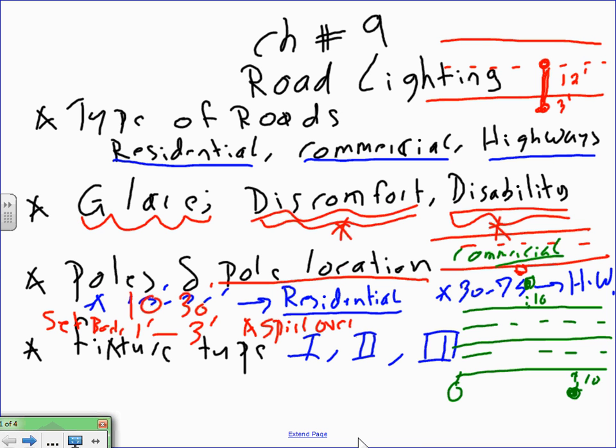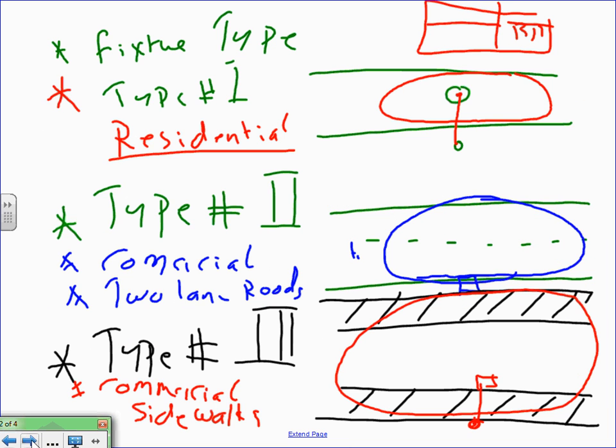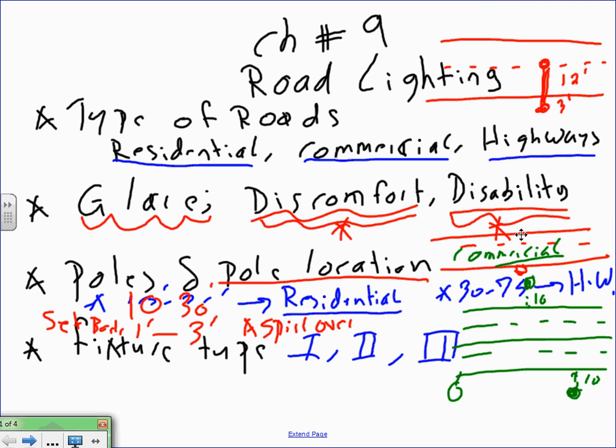I want to show you the types of. Okay, I do have them here in a second. So that's basically, I threw a couple of things here. Sit back. We talked about the sit back right in here. You usually sit back in residential, you will sit back 3 feet or so. So you put 3 feet and you set your pole and then you throw the light right to the center of your street. So any questions, guys, about the pole?